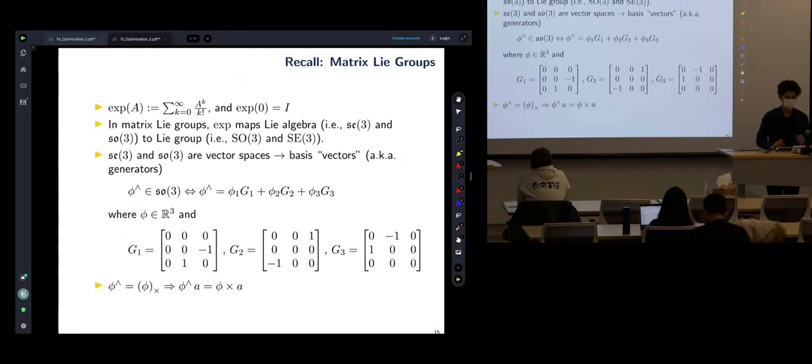So this wraps up the two topics that I want you to learn around the optimization, because you read them in papers, you see them as tools in libraries, and you want to know what does it mean to choose a robust kernel in G2O, for example, or in GTSAM. What does it mean to change that hyperparameter of Cauchy loss to be 2, to be 4? So you know that you're choosing that region to be bigger and smaller. You have an intuition about it. And the examples I gave you are simple enough that you can play with them and build more intuition around them.